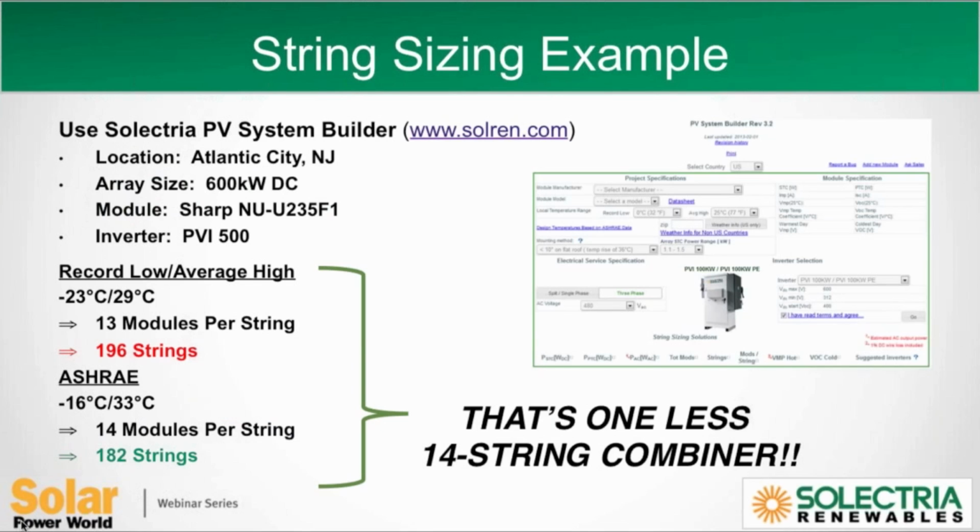It's a lot of the things that have already been discussed about oversizing. Rewind a couple years, and the price of modules was say twice what it is today, and as a result, designers and installers didn't want to sacrifice any production from any module in the array. That meant attempting optimal tilt angles and orientation. That meant not installing modules in shaded regions of roofs. And now with lower module prices, you can explore flexibility by using higher DC to AC ratios.